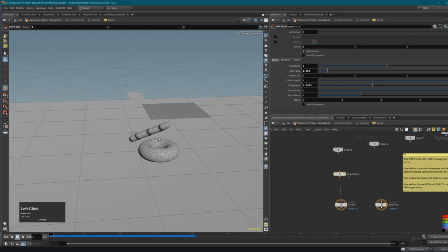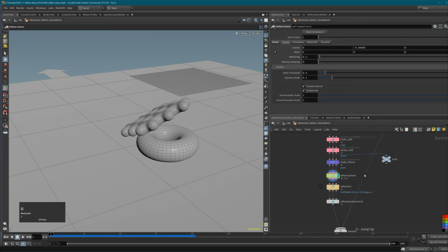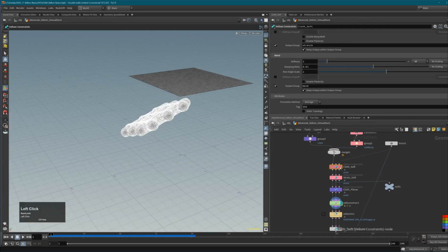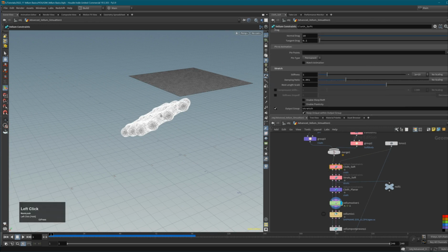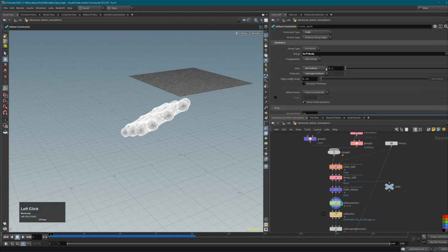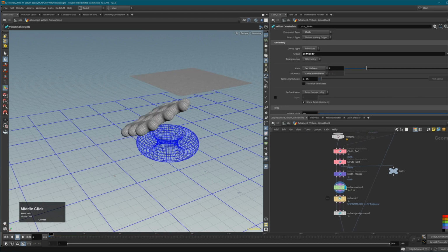And here I want to show you one thing that we discussed before, and this is mass. So if I go now to my soft body here on the cloth actually, and change the mass of my soft body, because I think that this is way too light. So let's go into our mass here and change this from 0.1 maybe to a value of 2, so it gets quite heavy. And then let's run this simulation again.